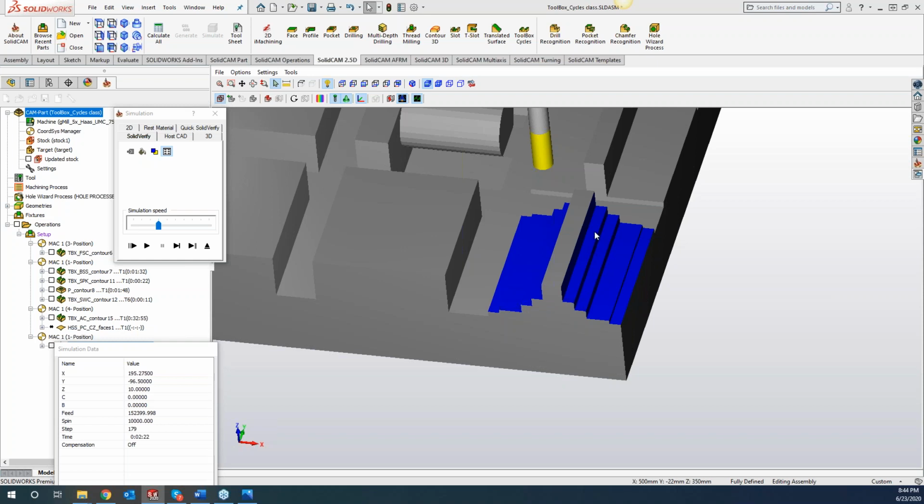So this is your ideal thin wall feature that works really good for taking those light cuts going back and forth. Now, this can be done in profile operation, but you would have to have a lot of operations to achieve what we're doing here. For it to bounce back and forth along with the levels, there'd be a lot of work and a lot of different operations.